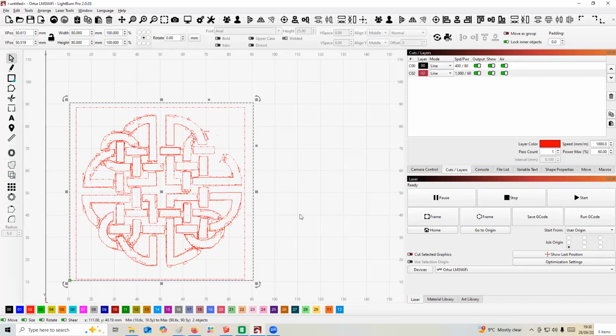It may drop through whatever base it is you're using underneath to stop the laser from burning any tabletop you're using. So what you need to do is make it engrave first, and it's dead easy. All you do is take the engrave, move it up, it automatically changed it for you. So now we're going to engrave, then we're going to cut.